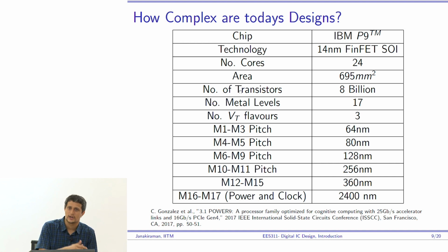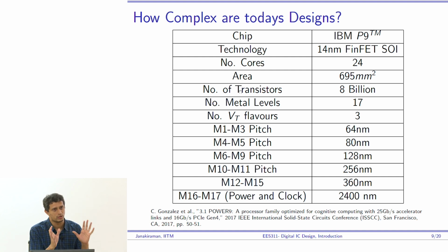They had to move to FinFETs, okay? And that is basically some 3D structure. I'll try to tell you at least what that structure looks like at some point when I do the transistor. But let's just take it for now. In 14 nanometer, to handle leakage current, you had to go to a radically new technology, okay, which also makes technology development very expensive, by the way.